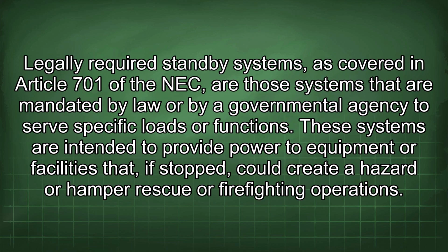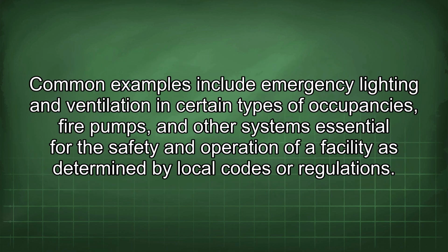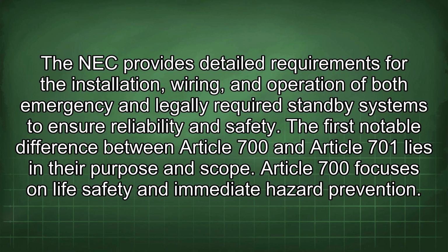Legally required standby systems, as covered in Article 701 of the NEC, are those systems that are mandated by law or by a governmental agency to serve specific loads or functions. These systems are intended to provide power to equipment or facilities that, if stopped, could create a hazard or hamper rescue or firefighting operations. Common examples include emergency lighting and ventilation in certain types of occupancies, fire pumps, and other systems essential for the safety and operation of a facility as determined by local codes or regulations. The NEC provides detailed requirements for the installation, wiring, and operation of both emergency and legally required standby systems to